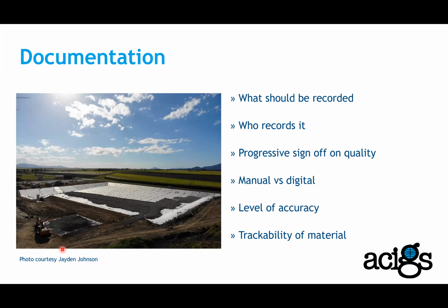Also, we have seen digital CQA, with QA engineers using tablets on site to keep the construction records, or they do it manually. So we need to have that discussion at the beginning of the project and find the best solution for that particular project. Level of accuracy, how accurate we want the documentation to be, and also traceability of the material. So we basically want to know each roll of the material, where it has been placed in the construction.